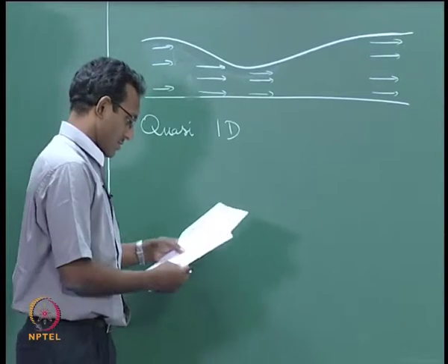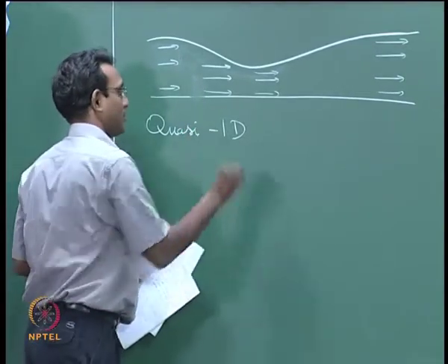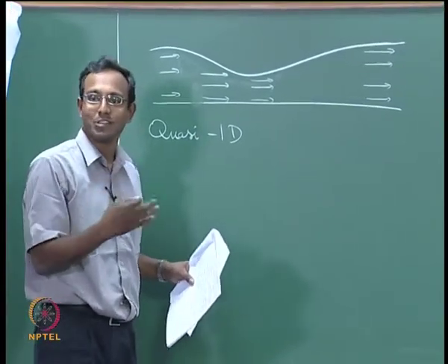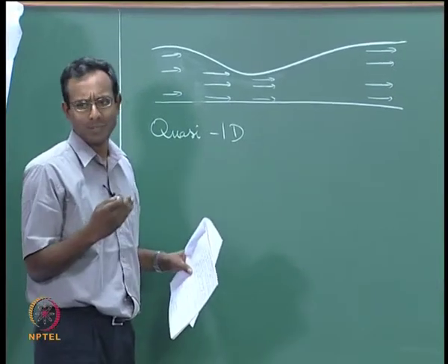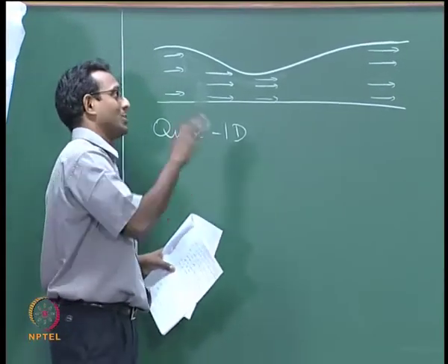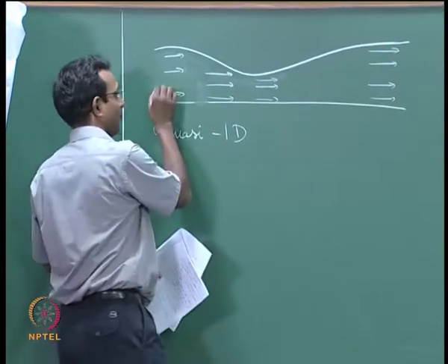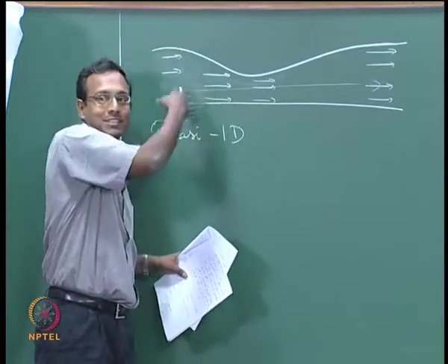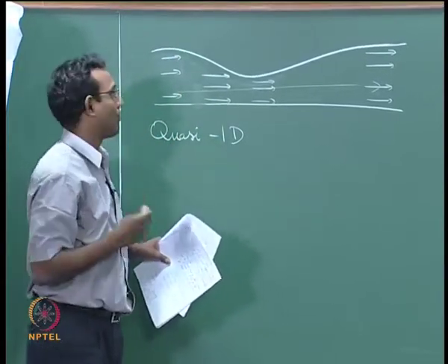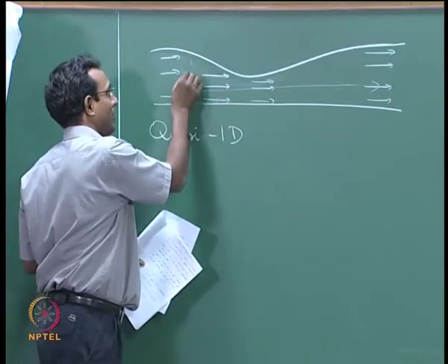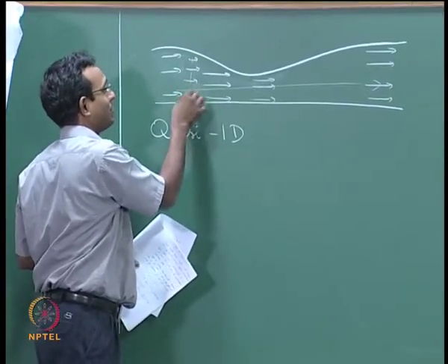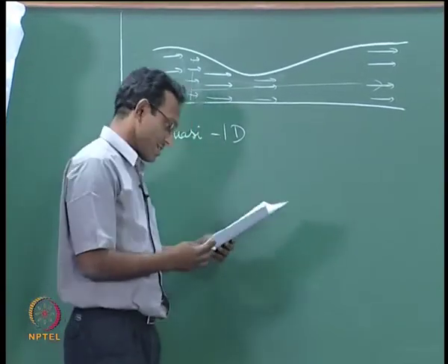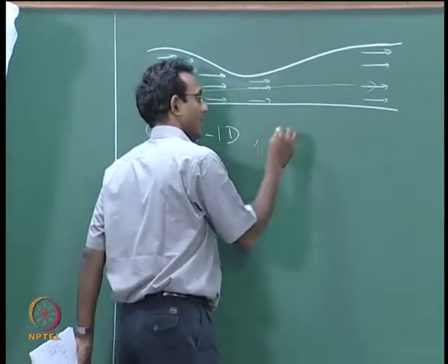Okay. When I say quasi 1D, I am just going to say stream normal direction velocity components are neglected. Stream wise components only. I am going to say all the velocity is along stream wise direction, which is for me in this direction for now. I won't worry about area variation, one side is more than the other side and all that. We will just assume locally I am going to consider some perpendicular line and flow is always perpendicular to it. That is a simple way of thinking about it, easier to convince myself that way. Okay. And of course, I am going to also neglect some things.